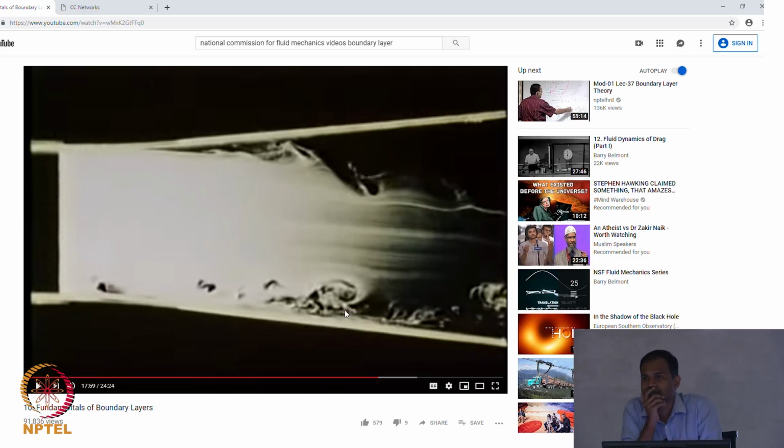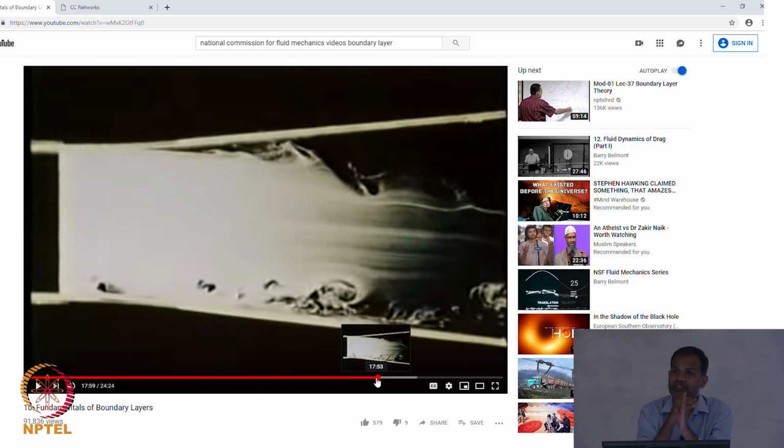Yes, do you mean the video or what I said? What I am trying to say is that turbulence corresponds to larger inertia. So the fluid that comes in has a tendency to maintain its velocity. Instead of having an opposite velocity, it has a tendency to go with the same velocity. Therefore, in a turbulent boundary layer, the chance of separation is less compared to a laminar boundary layer.